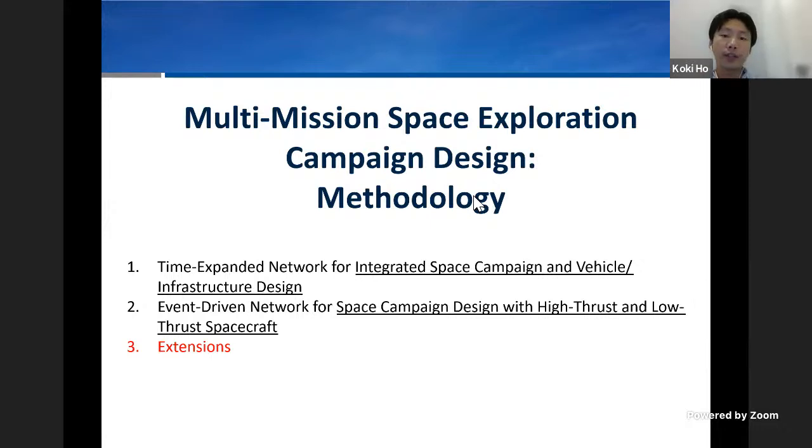Yes, definitely. I would say there are two ways to answer that. Some of the early work we did, the work I introduced here, uses mixed integer linear programming, or mixed integer linear optimization, because of the efficiency of solving it, and also because of the relatively simple network we have. This assumes that we can approximate the spacecraft model or trajectory model using a linear or piecewise linear function. But that's not necessarily true if we start to consider a higher fidelity problem.